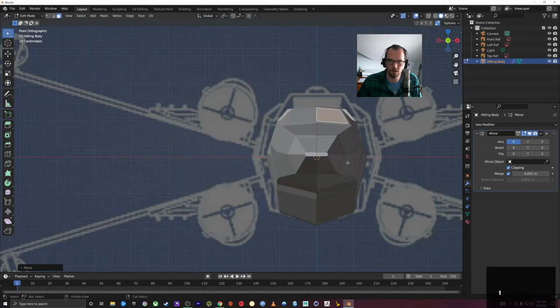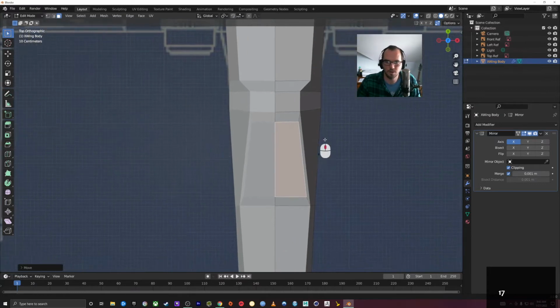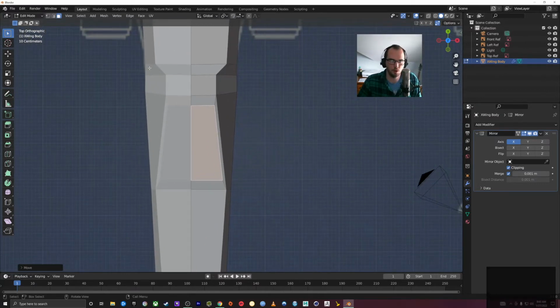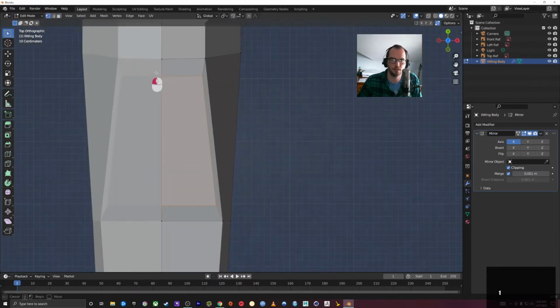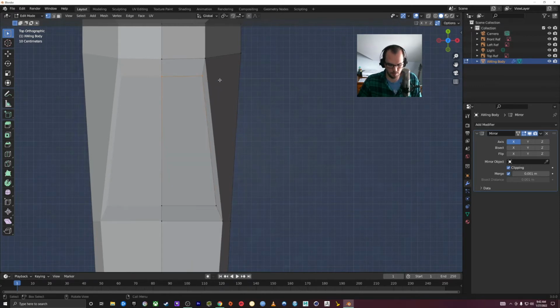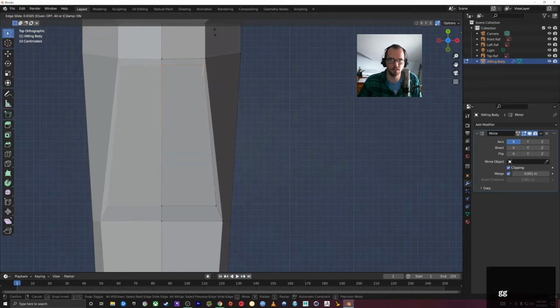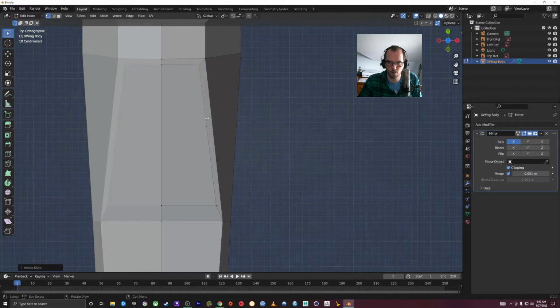And I want to do my top-down view because I want to get these points kind of dialed in. So I'm going to go 1 for vertex select, and I want to double tap G these ones to kind of slide it up a little bit. I'm going to double G this one to slide. Whoops. Double G to slide it this way a little bit, because I want a uniform size frame around this window here.